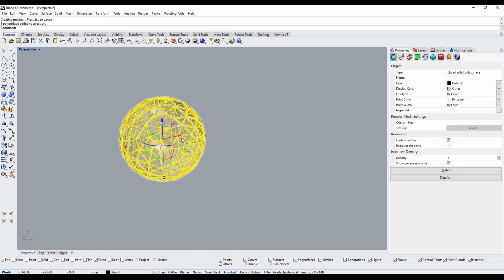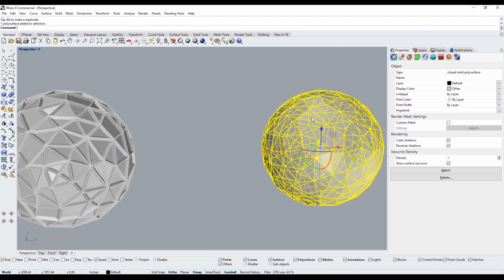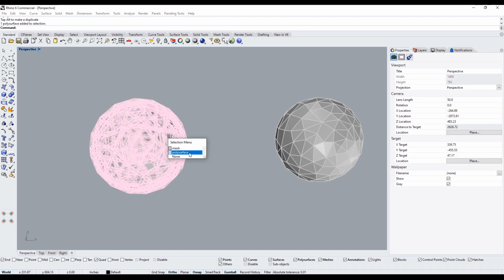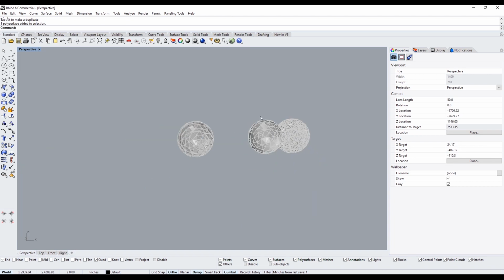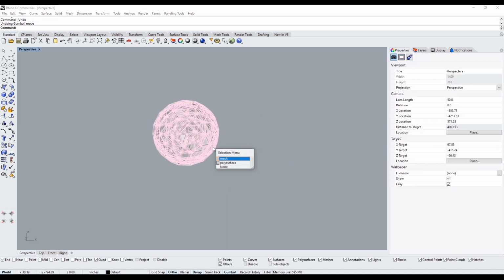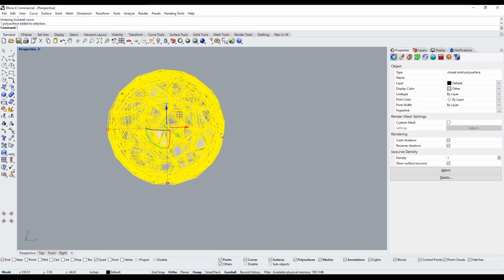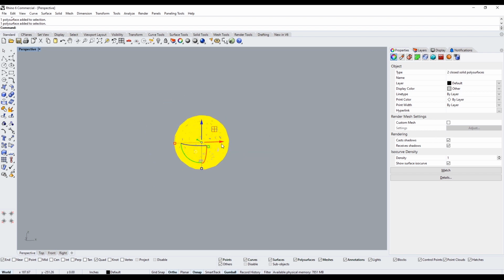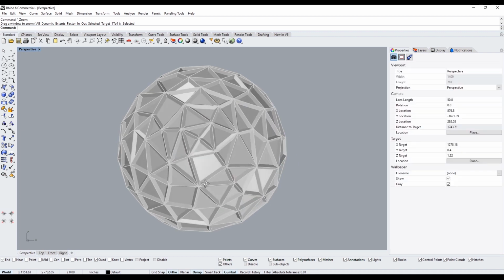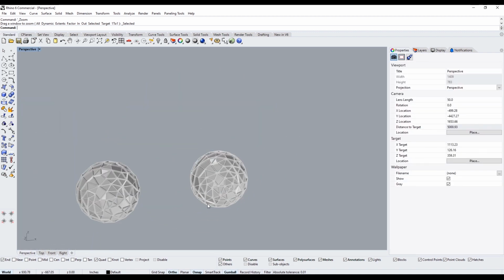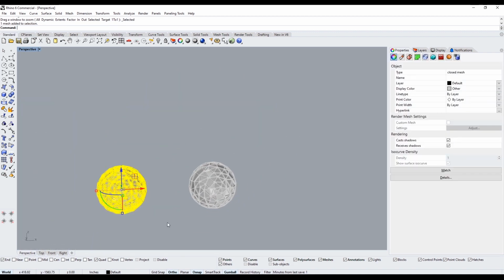and then we'll take the poly surface, move it to the right, and so that just gave us the inner portion. There's also an outer portion. So let's actually bring those back. This poly surface, this other poly surface, move it to the right. And here we have it as a NURB, so we can hide this one.